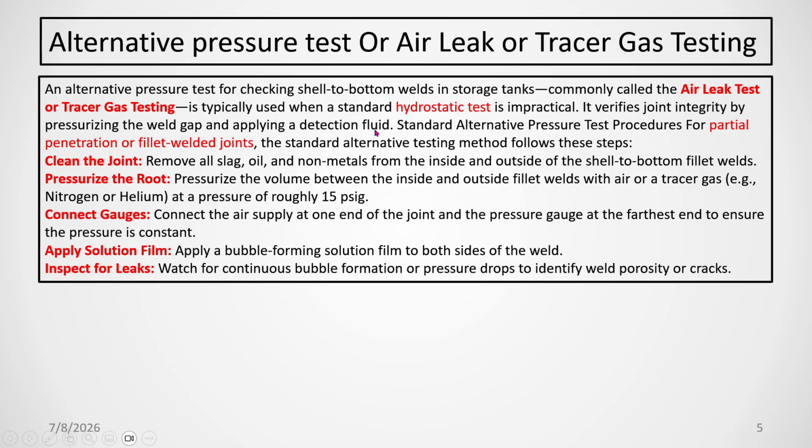So this type of leak test can be done. First you have to clean, pressurize, and then apply bubbles. If bubbles are coming, then you can say the leakage is there. Otherwise, leakage is not there.